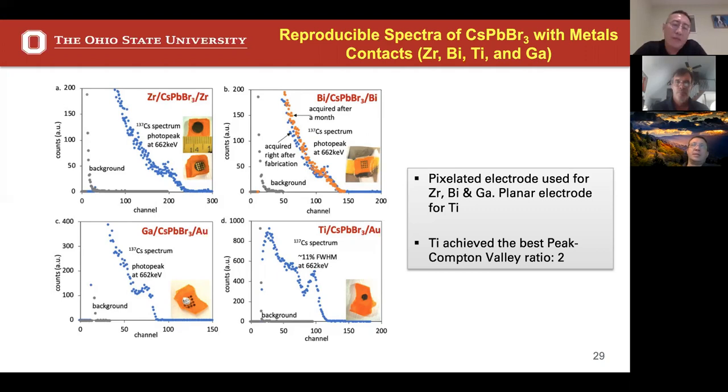I have another question. Well, just comments. You raised a good question about surface polishing for hybrid perovskite. We worked on that for a few years, and yes, we polished as well, but the problem is it's sensitive to the environment, which means after your surface process, it's better to encapsulate as soon as possible. We tried using epoxy to seal everything. People have used wax to seal the device right after polishing to maintain the surface structure. Otherwise, you're probably going to react with moisture in the air.